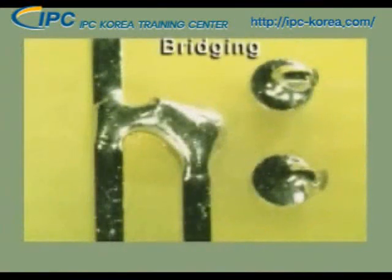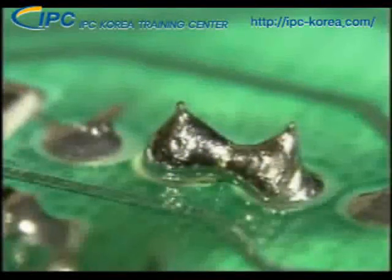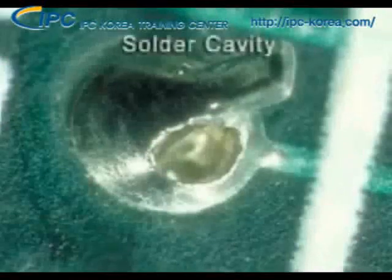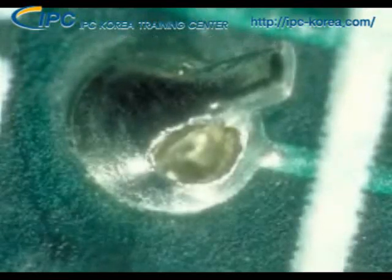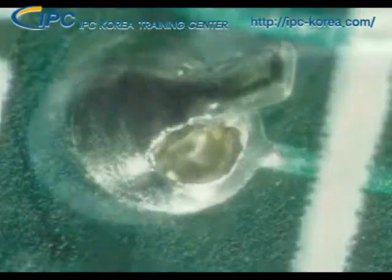Solder bridging is a connection of solder across conductors that should not be electrically joined together. This is always a defect since it misdirects the electronic signal. A solder cavity that does not reduce circumferential wetting of the lead and barrel, the land coverage, or the vertical fill below the minimum acceptable requirements is considered a process indicator.